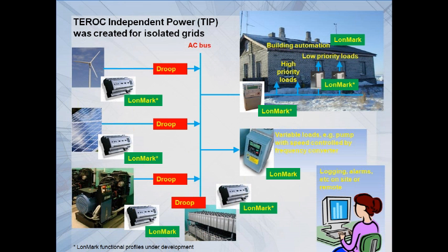All of these devices can be integrated so they together form a control system for the supply, storage, and demand. It is an open system where the control devices have interfaces according to Landmark guidelines, and they communicate with a standardized protocol, which can use a variety of media. One very useful way of communicating, especially to meters and loads, is to use the existing power lines, which I will come back to later.